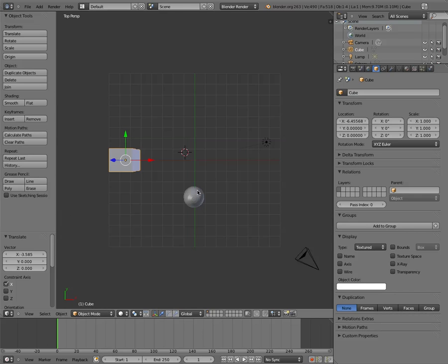So if I wanted to put this little crosshairs where my new object is going to be directly in the center, the first thing I would do is go directly top by hitting the 7 key, click there, and then I would hit the 1 key and click there. And now, for all intents and purposes, that cursor is in the center.